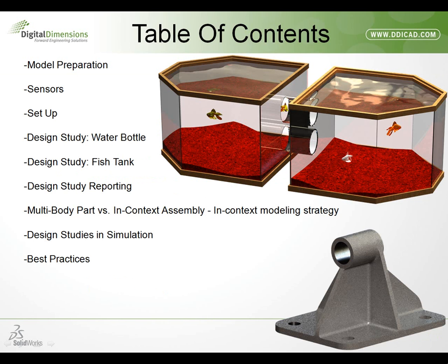Design studies is the function of taking a model and telling SOLIDWORKS to flex or change a few dimensions, recalculate the result until it meets a predetermined goal. In order for this to work properly, your model requires good, clean design intent. That is, you built it with change in mind. You know how the part's going to change when you flex the dimensions.